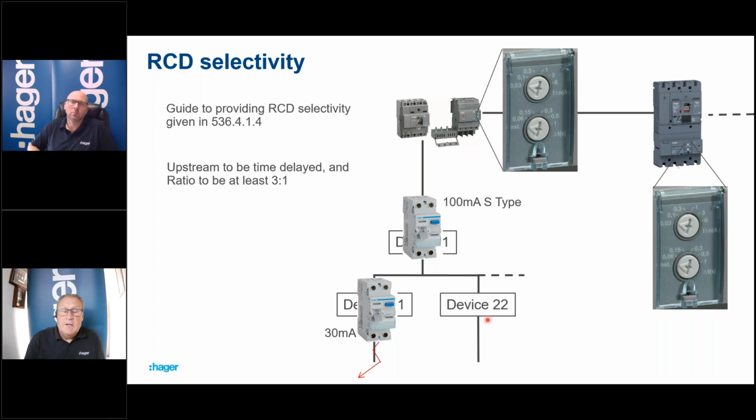Now, if we, for whatever reason, need an RCD upstream of that, normally we'd have some kind of MCCB stroke RCD add-on or modular RCD functions from that lot. If you remember from the first slide, you might have seen it here, RCD attachments, quite commonly for MCCBs, or we can use the components of an RCD, a toroid detector, and a trip device that goes inside. It's the same thing essentially. It'll provide you with an RCD that will trip under residual current.